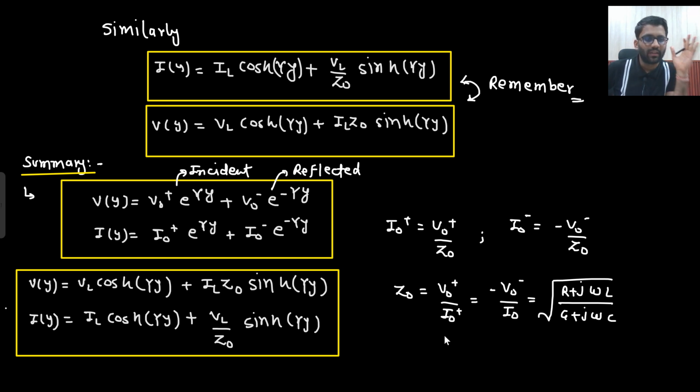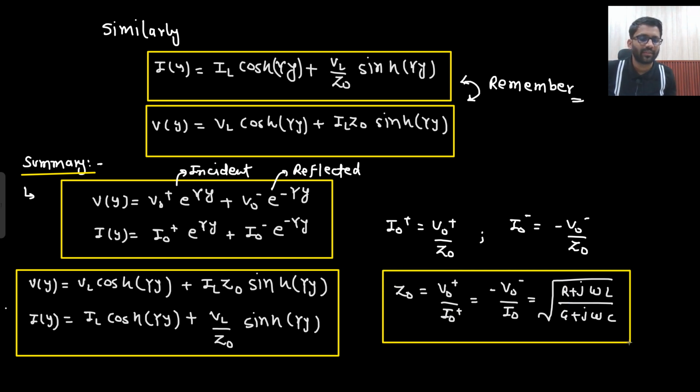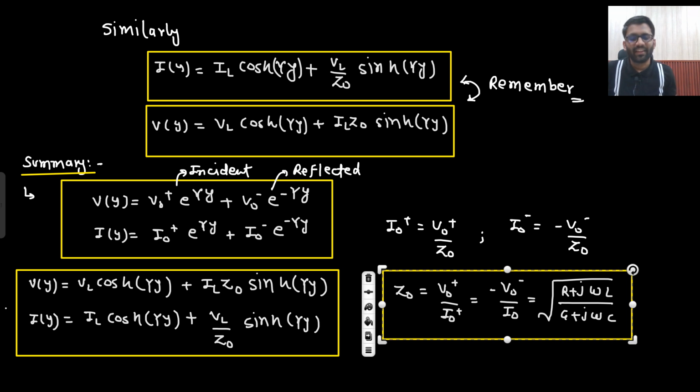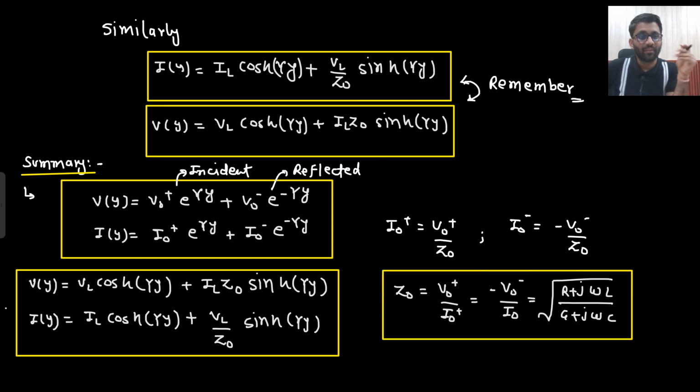So till now in our discussion, you need to understand that the transmission line is RLGC, and then these equations. That's it. We have spent roughly 70 to 80 minutes, and this is the only summary. Well and good. Now we understood this impedance. Sorry, not intrinsic impedance, characteristic impedance. Intrinsic impedance is the term used in EM waves, so here we use the term characteristic impedance.